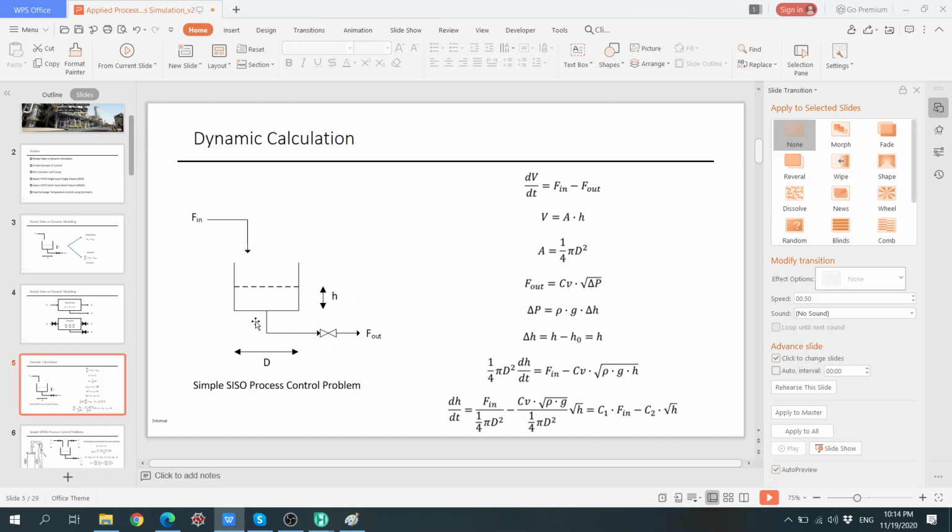So the dimension of this equipment, we need to know this. And also the dimension of this equipment, we need to know that. If we have a heat exchanger, we need to know the dimension of the heat exchanger. If we have a pump, we need to know the dimension, or at least the head and the pressure of the pump, the performance curve. So in dynamic, because it's more complicated, we need more data, and for dynamic to run smoothly, we have to size this equipment accordingly, or if we already have the size, we need to put that size into the simulations.